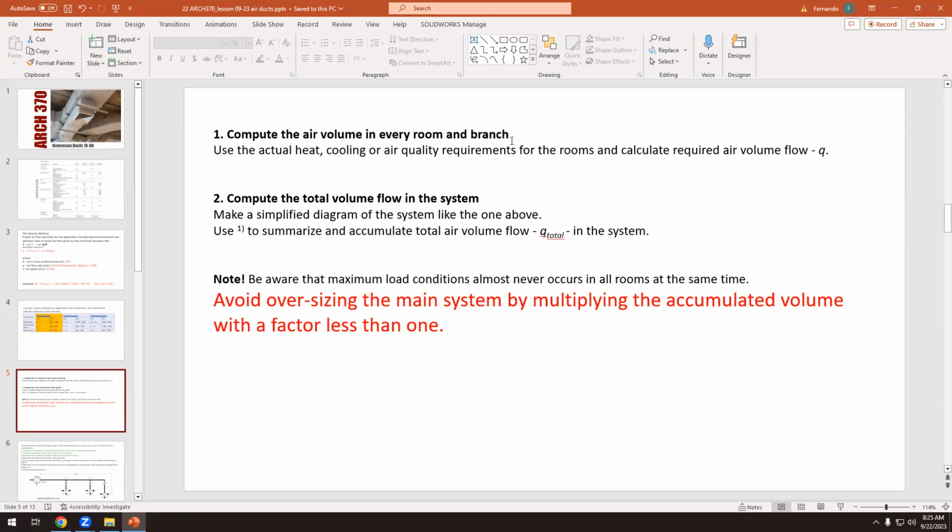Why can't you use the same file that you used before? Well, if I have to change the size, I'll do it, but changing the size, you have to go duct by duct. And then all the fittings, you have to select all the fittings and change the size as well. So I think it will take longer than starting from scratch. So we are going to start from scratch. We're going to do it again, because the goal here is to practice. So we have to do this time and time again. So we're not fixing what we did last time. We are starting from scratch. And then we have to check the velocity, and this is what we are going to do now.